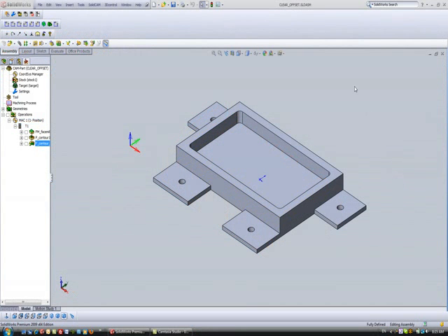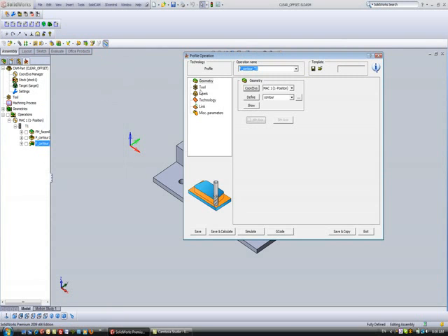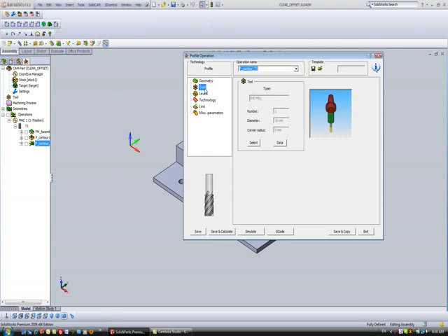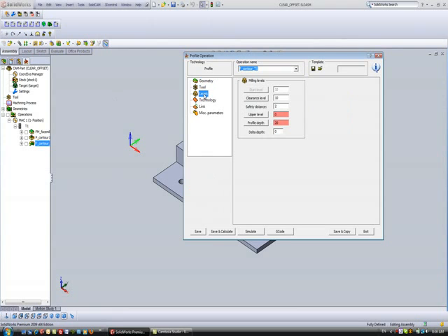Now in this part, we'd like to show some of the improvements that we've added for clear offset on the part. What we would like to do is mill out these steps with a 10 millimeter end mill, but the length of this area itself is 40 millimeters. So what we'll do is we'll be using the option of clear offset to step in on that step itself. If I open my operation, you'll see that my geometry are those areas over there, those 4 edges. My tool is a 10 millimeter end mill. My level is down to the bottom step.